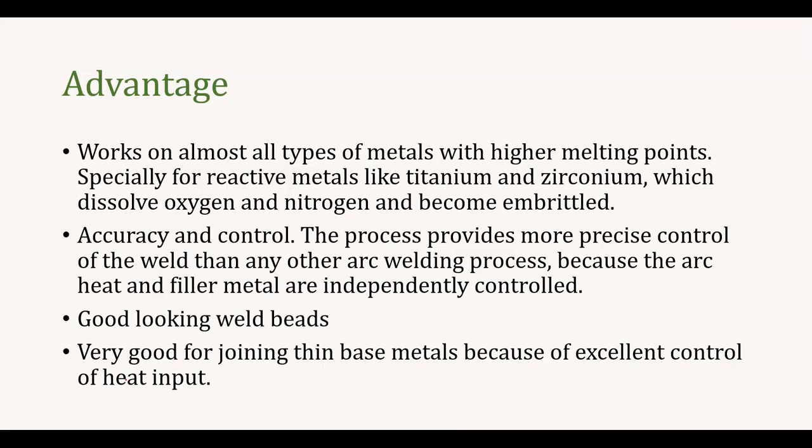So coming to the advantages, it works on almost all types of metal with a higher melting point. As the name implies, you can see both ferrous and non-ferrous materials can be welded using this TIG process, and especially reactive metals like titanium and zirconium, which dissolve oxygen, hydrogen, and nitrogen and become embrittled. Such reactive materials also can be welded using the TIG process.